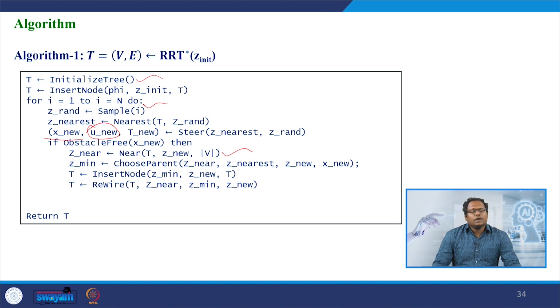node is ready to get connected, instead of connecting it directly as in the case of RRT and RRT connect approaches, we take a neighborhood of this new node, and in the new node neighborhood we have chosen several nodes, and from that node to the initial node we connect and see the length which is minimum, that will be the final node, thereby ignoring or avoiding the other nodes.